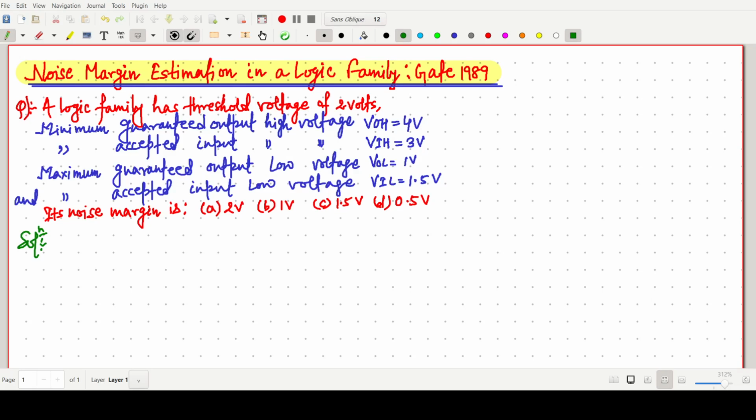Welcome everyone. In this video lecture, we will solve a GATE 1989 question which is based on the noise margin. In this question, it is given a logic family has threshold voltage of 2 volt and the minimum guaranteed output high voltage, that is our VOH, is 4 volt. Minimum accepted input high voltage VIH 3 volt, maximum guaranteed output low voltage VOL 1 volt, and the maximum accepted input low voltage, that is our VIL, 1.5 volt.